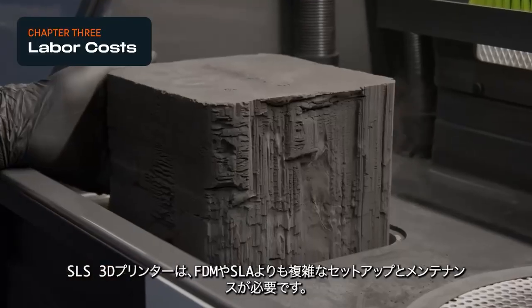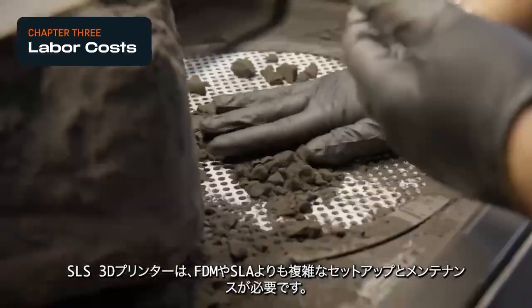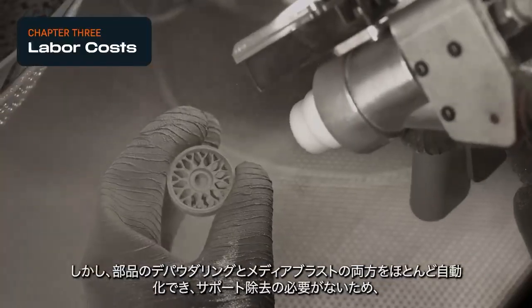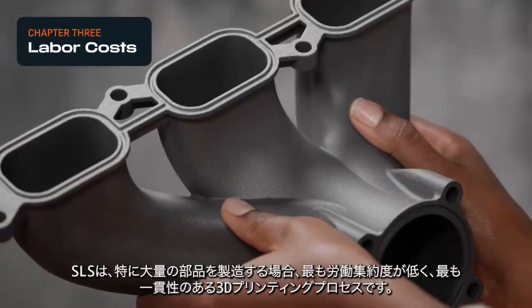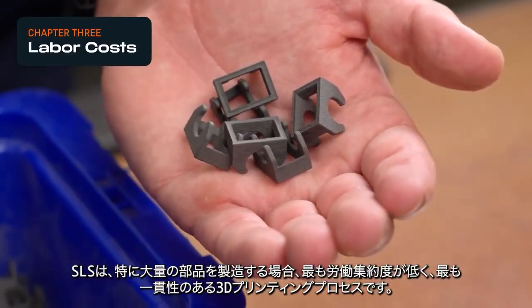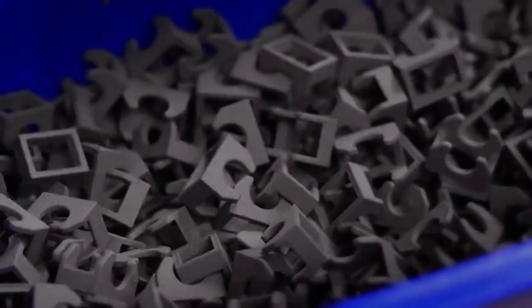SLS 3D printers require more involved setup and maintenance than FDM or SLA. However, as both depowdering parts and media blasting can be mostly automated and there's no need for support removal, SLS is the least labor-intensive and most consistent 3D printing process, especially for larger volumes of parts.